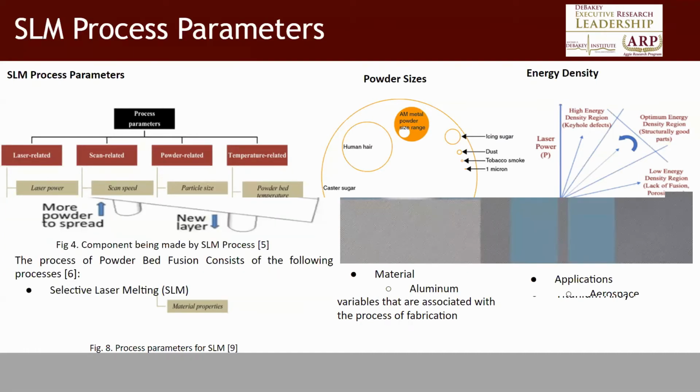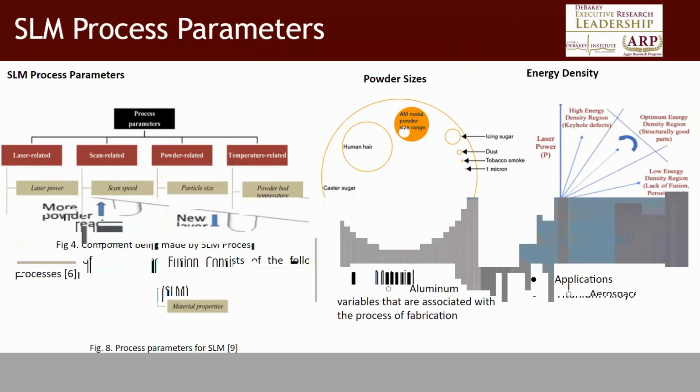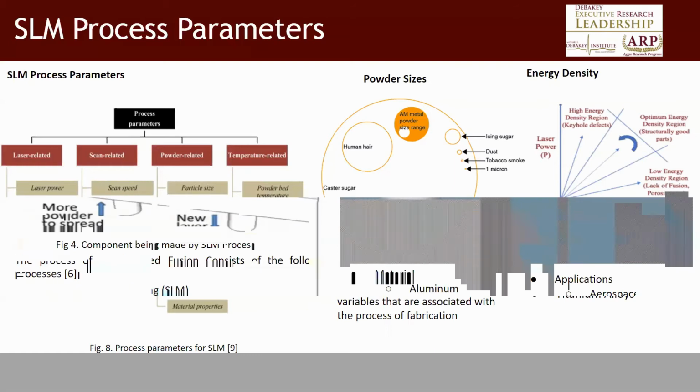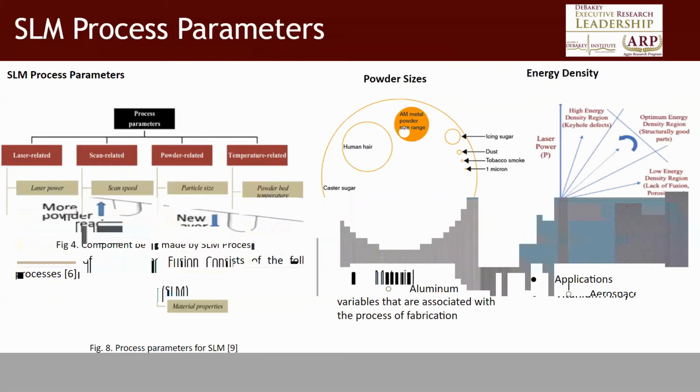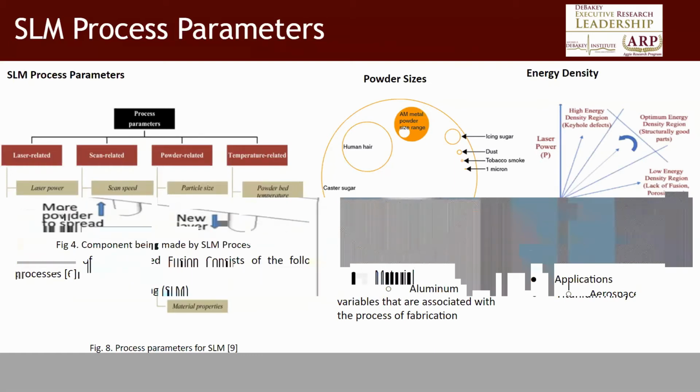Variables like the powder size: will the powder flow well, will the powder metal fill up the fabrication area well, and many more questions must be asked. Process parameters associated with the laser can either produce a high density part or produce holes in porosity. Although there are many process parameters, perfecting those can produce parts that are specified to applications and produced through a lean process.